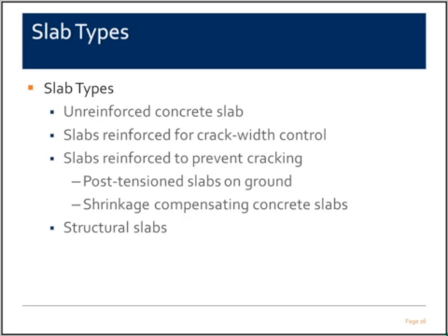And structural, you can have a structural slab. The structural slab will have a good amount of reinforcement to be able to span over any areas of loss of support, or in swelling soil areas, you might use these things. And technically, like in your basements, if you have a post supported directly on the slab, it should be considered as a structural slab, but most often it won't be designed as one. They'll just put in welded wire reinforcement and design the slab that way, 3-4 inches of slab.